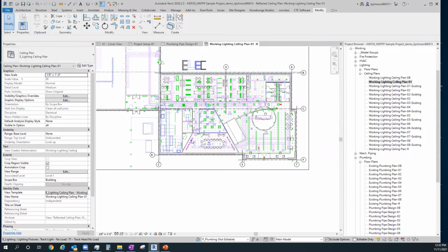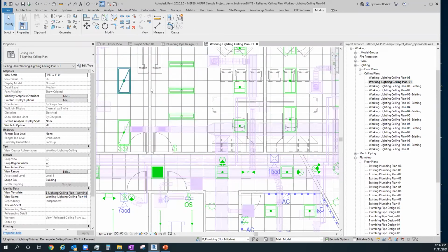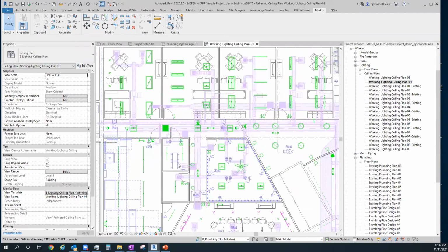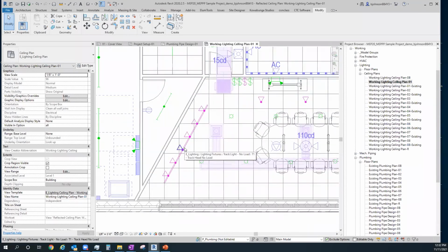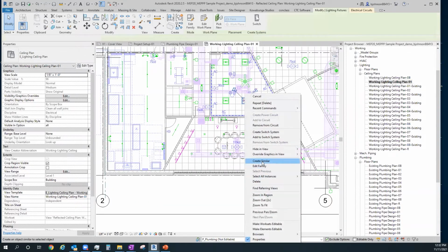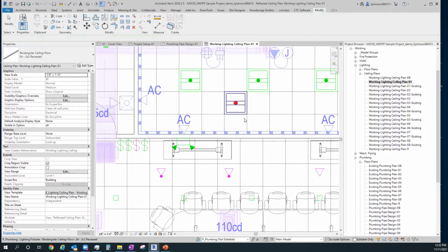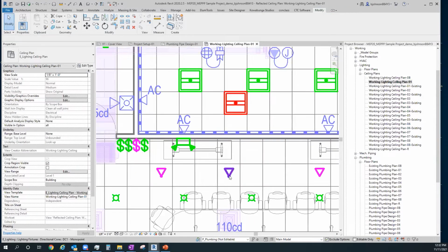Regular hosts do not. One of the other things in our electrical plans, everything that is green has been circuited. Anything that is magenta knows that it has a logical circuit, but it doesn't actually have a fully made circuit in that case. So if I could do a create similar in this case, I'll do a place on face and stick that in there. And when it does that, it turns red, right? So what's the difference between red, green, and magenta?